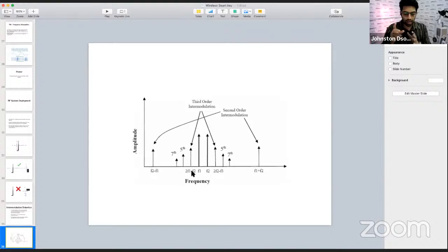Always remember, digital wireless, at least in live sound, is there only for microphone systems. In-ear systems still work on analog, because in-ear systems the cost would go very high, because you need stereo channels. So you'll need two A to D converters and two D to A converters. Everything is going to double up, and the cost is also going to spiral up.